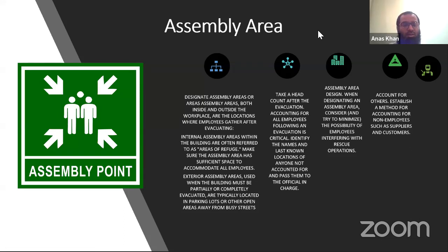Now this is an additional thing which is not in your book, just for your information. Assembly point. In oil and gas and on construction projects we used to say muster point; in other companies and places we say assembly point. The assembly point is where you gather in case of emergency or evacuation. Always remember, it is not a requirement to have only one assembly point. You can have more than one, but the people working in the area should know which assembly point they have to reach.